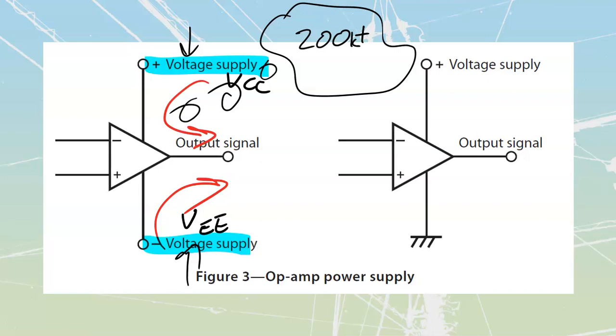Okay, let's talk about this input side over here. The input side of our op-amp can be thought of as if it were a very, very small voltmeter across here. You should know a couple of things about voltmeters. You should remember them from first year. A good voltmeter is going to have a very, very high value of impedance or resistance. So it's going to be a super high value of resistance, which means that the current that is coming into here is going to be tiny.